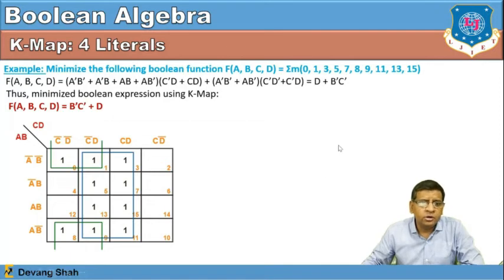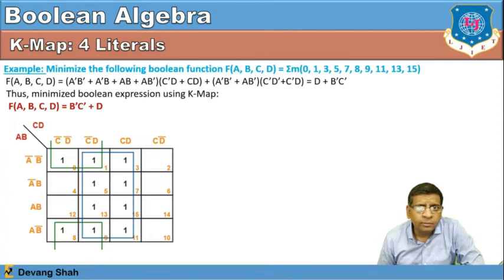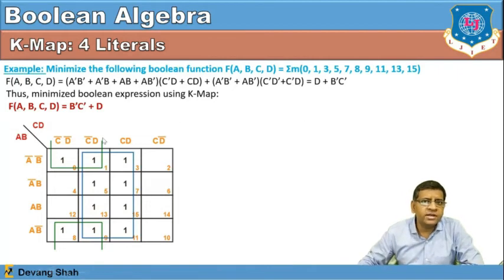Once you put them, your first job is to draw the K map having 16 blocks of A, B and C, D pairs, like 00, 01, 11 and 10, right? You can now put the corresponding 1 in the respective min term blocks. Is a group of 16 ones possible? No. Can you go for 8 ones? No. But 4 ones possible? Yes. You can check the 4 ones of adjacent blocks 1, 1, that is possible, but with an empty block in between the 1 1, this is not possible.